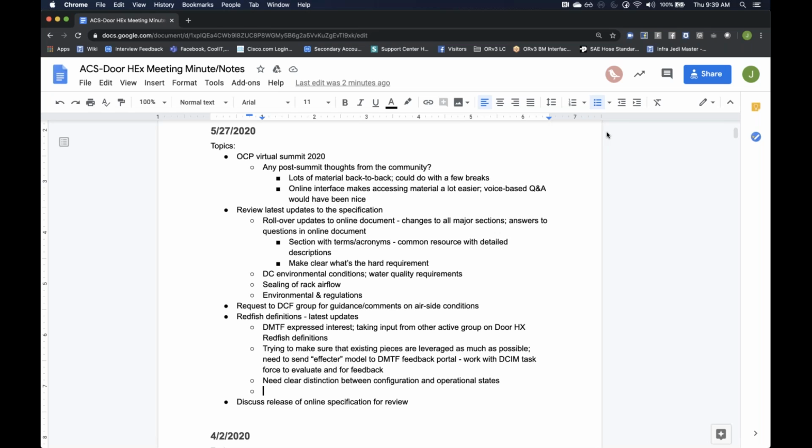So the manufacturer will enable all of those capabilities. There may be other capabilities that the controller has firmware for but are not enabled on a particular rear door cooler. But when the rear door cooler is installed, the customer has a particular idea of how he wants to manage the water flow and the airflow. So he would go into the configuration state and say, I want to manage this by differential water temperature.